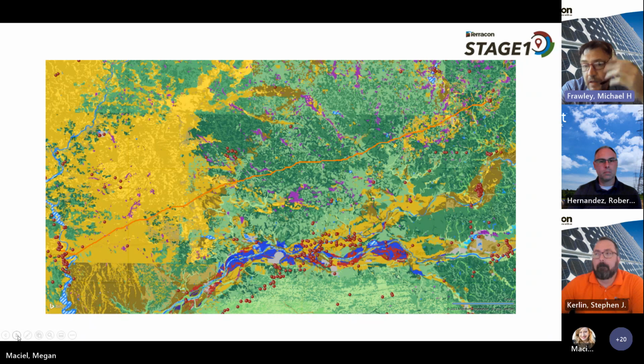as a geotechnical engineer. My background's predominantly in geotech. I've been doing this about 20 years. I was a senior geotech PM before switching over to lead the stage one group. So generally speaking, I don't expect you to know this, but if it's yellow, that's typically sandy material. And what this is representing is conditions in the upper 10. We could change that depth if we wanted to. And 10, I mean 10 feet. So in the upper 10 feet, we'd expect sandy material everywhere that it's yellow.